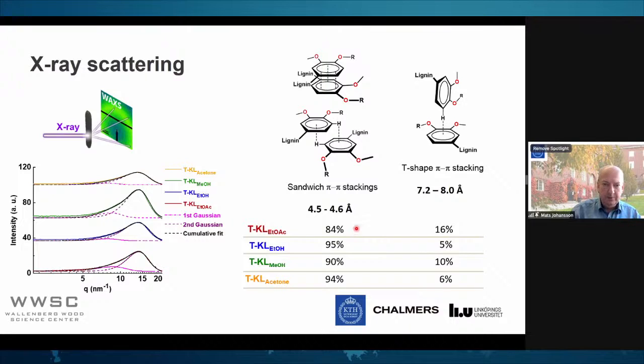Now I'm going back to what we take as traditional synthetic thermoset polymers, where you have evenly distributed aromatics like isophthalic acid, for example, in a polyester, randomly distributed. But when we start with the lignin fraction, they are coupled internally in a way that might allow more of this pi-pi stacking to occur within the thermoset structure. And the key question, of course, is, does this affect the properties?